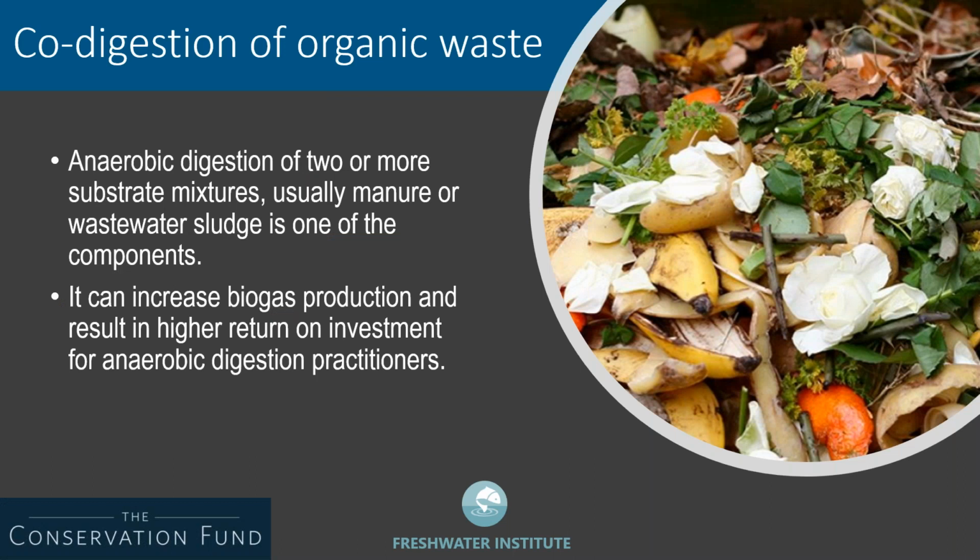So while I was doing my PhD, I worked on co-digestion of gummy vitamins with dairy manure. I was working on dairy farms in Maryland, Pennsylvania, and New York, and on one of those farm visits, we saw that a farmer was interested in using gummy vitamin waste as a co-digestion feedstock for their dairy manure digester. And they wanted to know whether they could add this material to their digester to further increase the biogas yield. We were intrigued, obviously, and so we took this material and conducted a biochemical methane potential test to quantify its methane potential. We mixed the gummy waste with dairy manure, and the results showed that the addition of gummy waste resulted in a 5-fold increase in methane yield when we compared it to digesting dairy manure by itself.